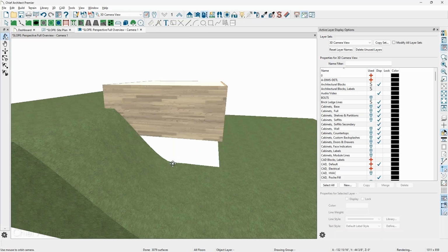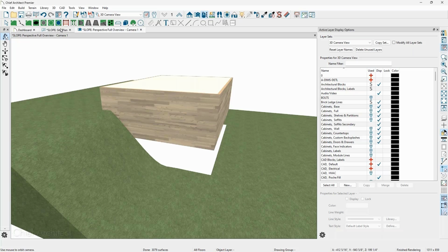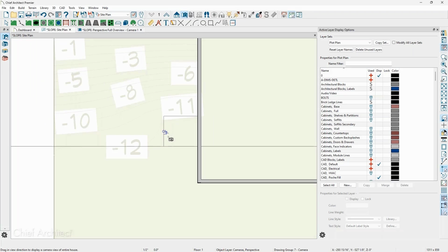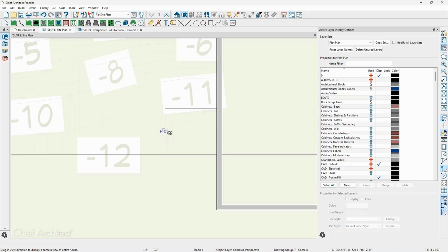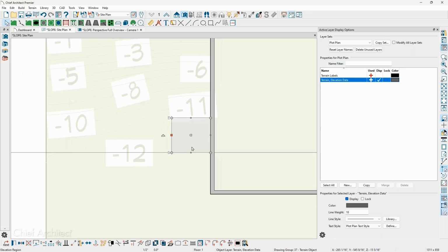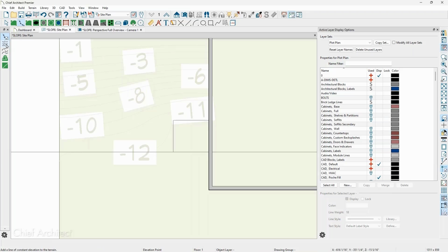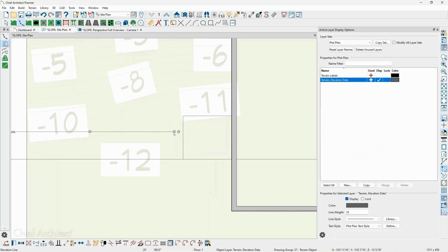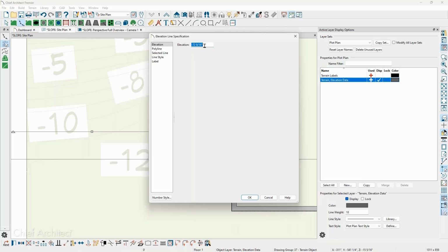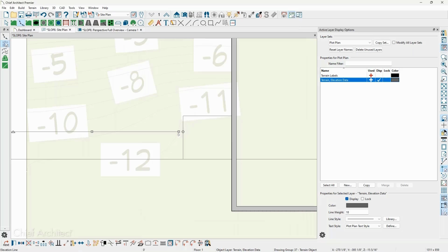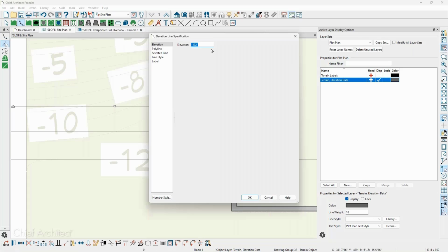Well, that's not showing that well, but what that did is pull that in, and if I wanted to shape that in any other way, I could shape it just using that terrain contour. It depends on how you want the lines coming in. If it gets real steep, you can also use the elevation lines. It's important that I wouldn't cross this line into the other one, but if I said this line is minus 11 feet, and then we'll make one more copy of that and pull it up and over just a little bit, and then say this one's minus 10 feet.